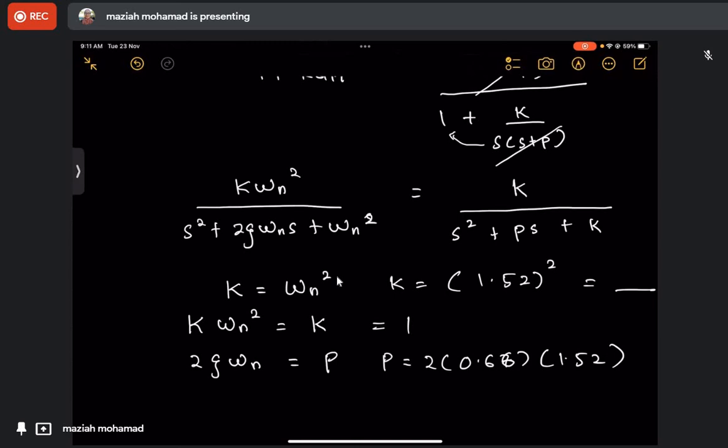Okay, so you can see the flow is reversed. They give you the specification. It gives you the parameters, actually, the maximum overshoot. It gives you settling time. So we determine the value of zeta and omega n from there. Okay, and then we're going to design the transfer function based on that.